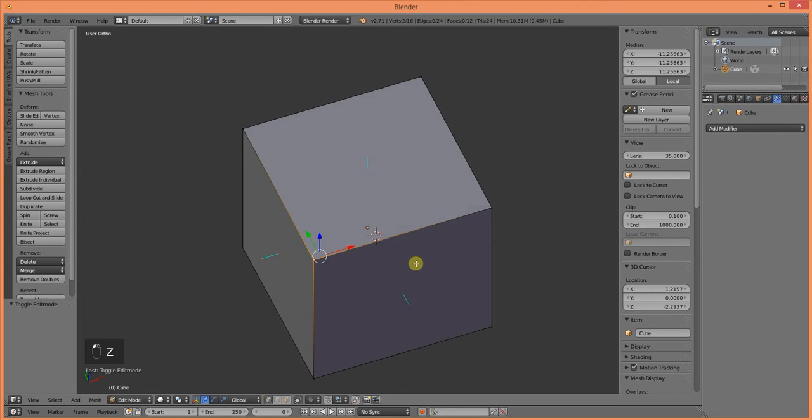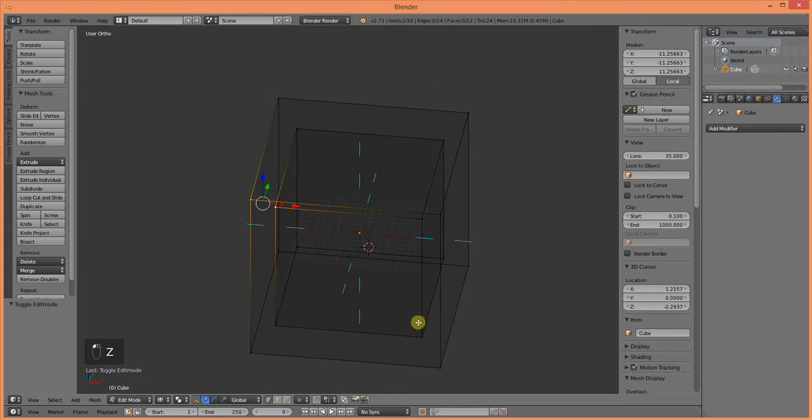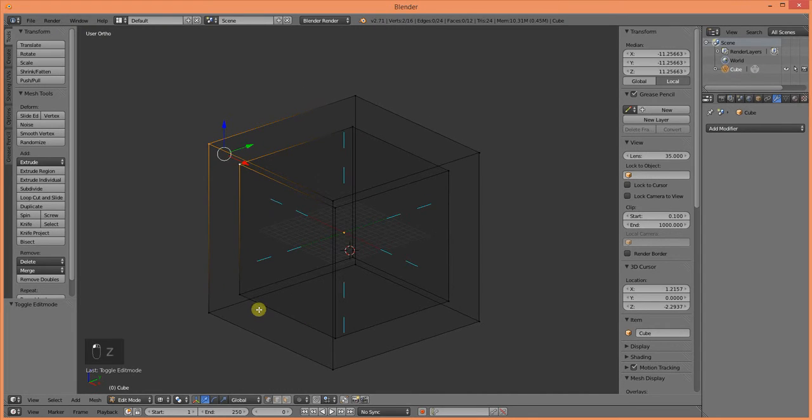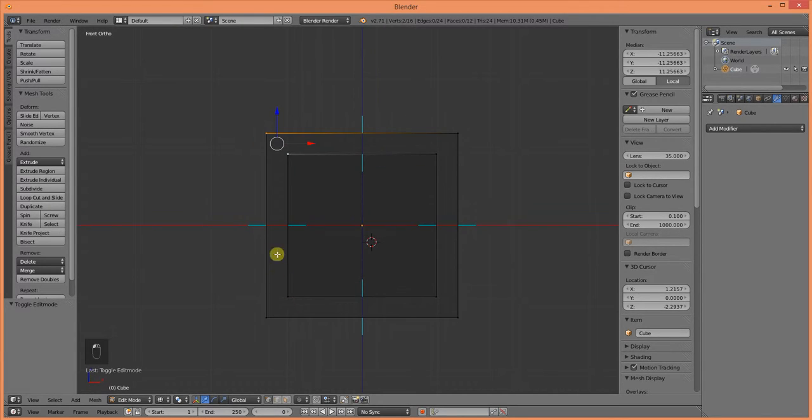If I were to drill a hole through this, then I will be able to see that hollow core in there. If I were printing this with supports, then of course it's going to be full of all the supports rather than an infill. All this area right here will be filled in with infill, depending on how many layers I have for solid infill or what percentage of infill I have.